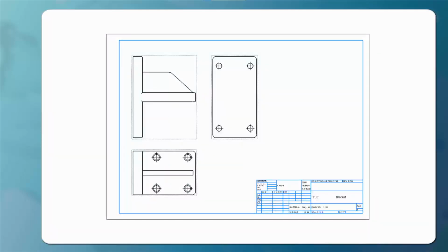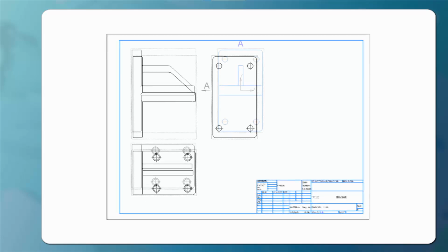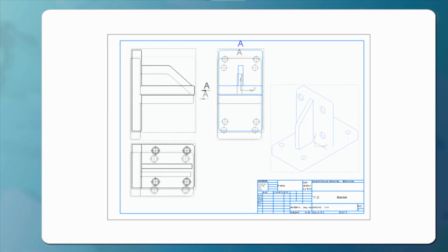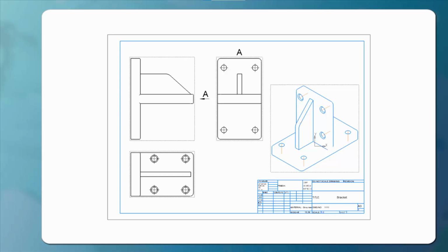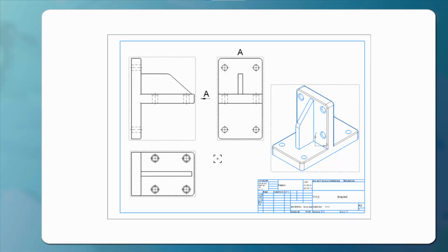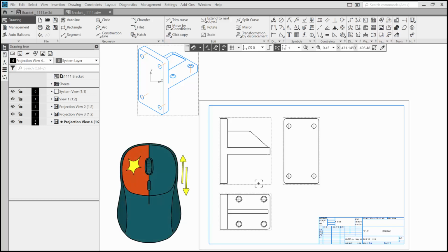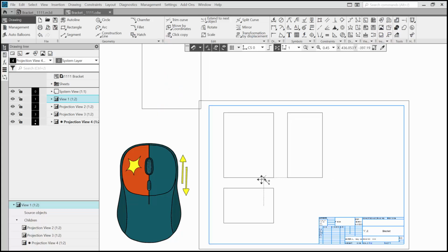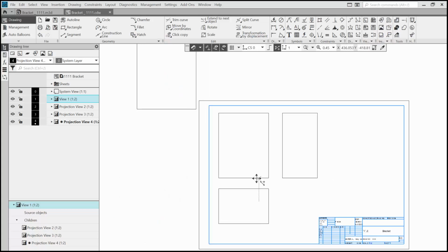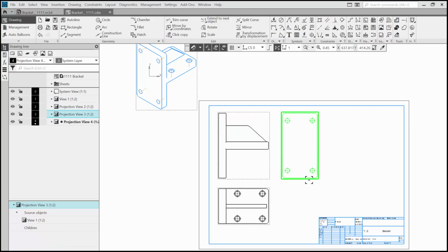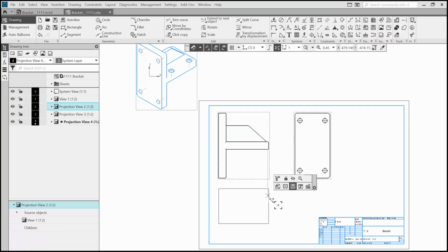In this video, we'll replace the left view with the right view, find the optimal isometric view, and arrange all views in the drawing. Let's move the views to fit them within the drawing sheet. If you try to drag the front view, all the views will move together. If you try to drag one of the other views, you can move them along the projection lines.